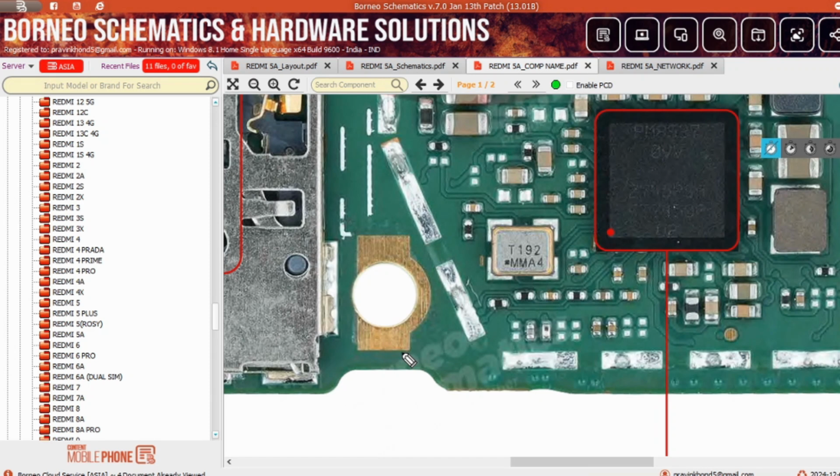It also helps the power IC with the boot sequence in the latest phones. So the power IC knows how to produce the first voltage, then the second, then the third. Basically a timing sequence. Got that?